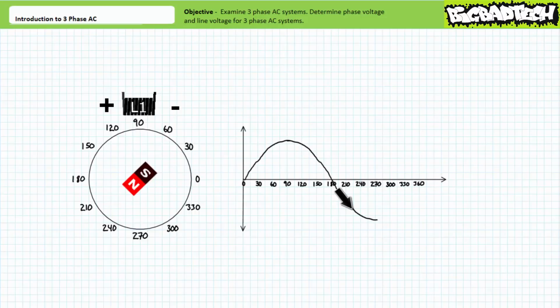In this scenario, we're assuming negative voltage simply means a swap in polarity such that plus to minus is oriented clockwise. When the South Pole is aligned with L1, an occasion in which the North Pole is at 270 degrees, induced voltage achieves a negative peak value. As the south pole recedes from winding L1, induced voltage is still negative, yet decreasing in magnitude.